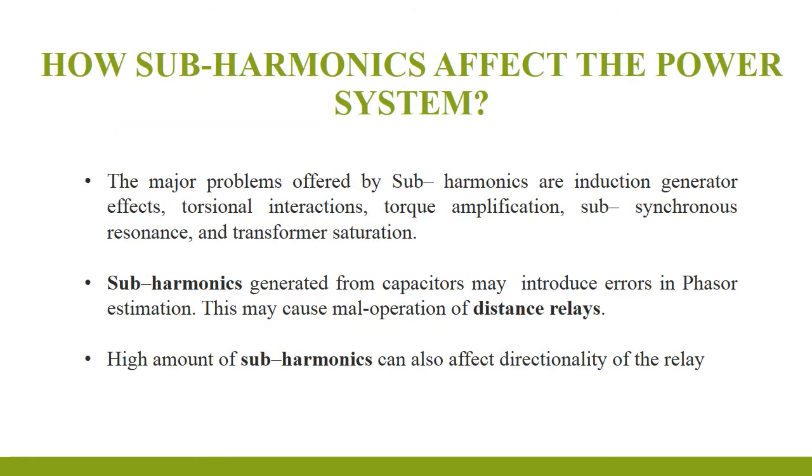How do subharmonics affect the power system? The major problems offered by subharmonics are induction generator effects, torsional interactions, torque amplification, subsynchronous resonance, and transformer saturation. Subharmonics generated from capacitors may introduce errors in phasor estimations. This may cause mal-operation of distance relays. A high amount of subharmonics can also affect the directionality of the relay.